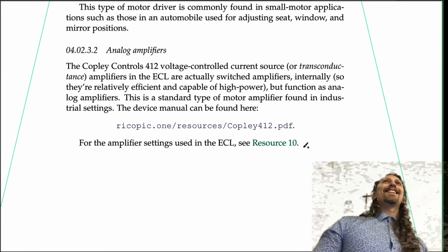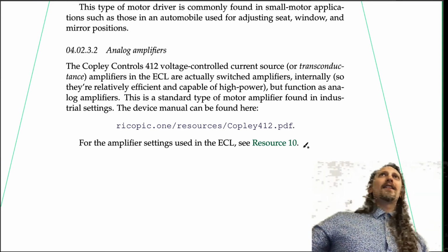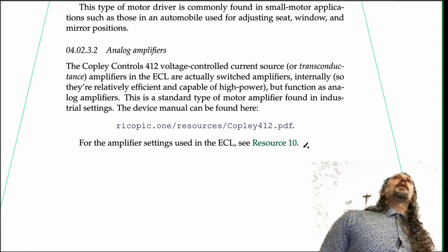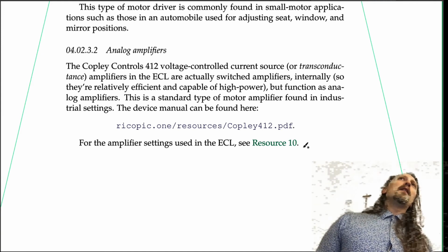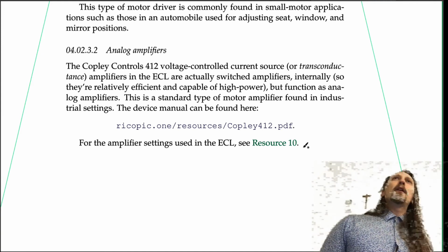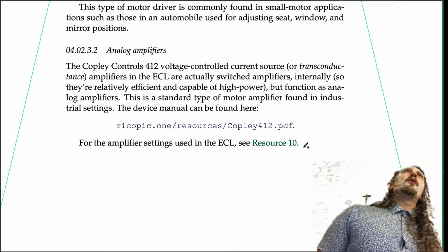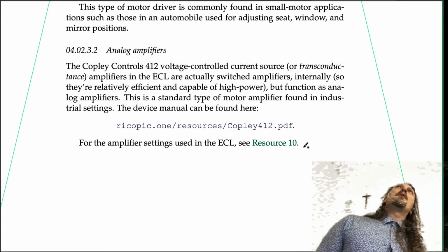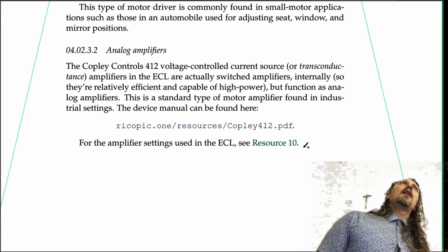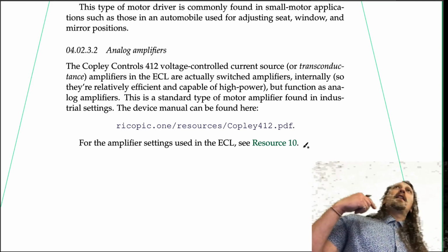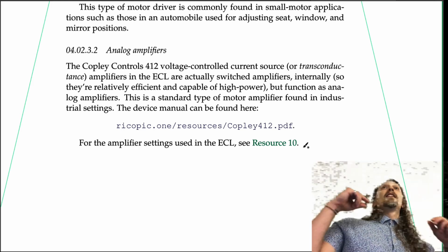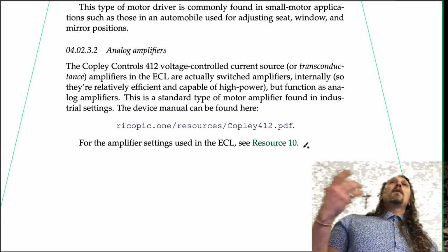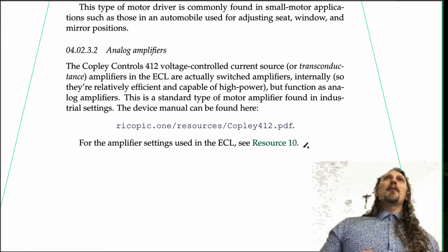Ooh, a question. Can you do pulse width modulation on like a stepper motor? Ooh. Stepper motors are just a very weird type of motor. They're almost a special case. I don't know. I've never seen anybody try putting in PWM because the operating principle of a stepper motor is that you put in a pulse with enough power behind it, and it will turn a certain increment.